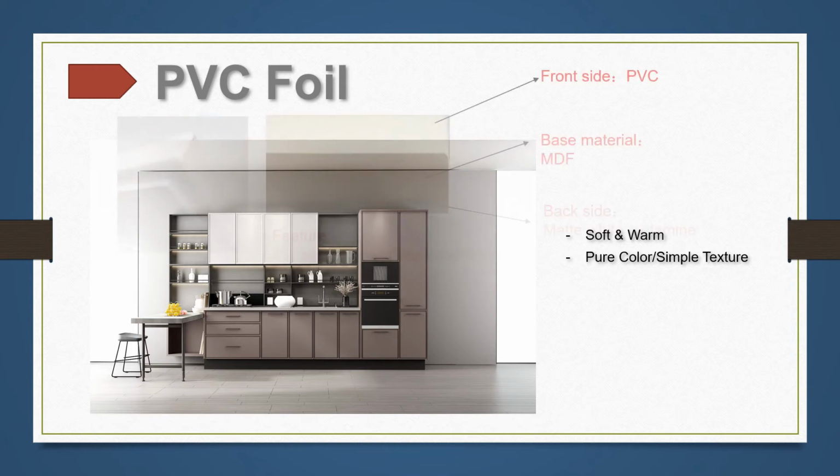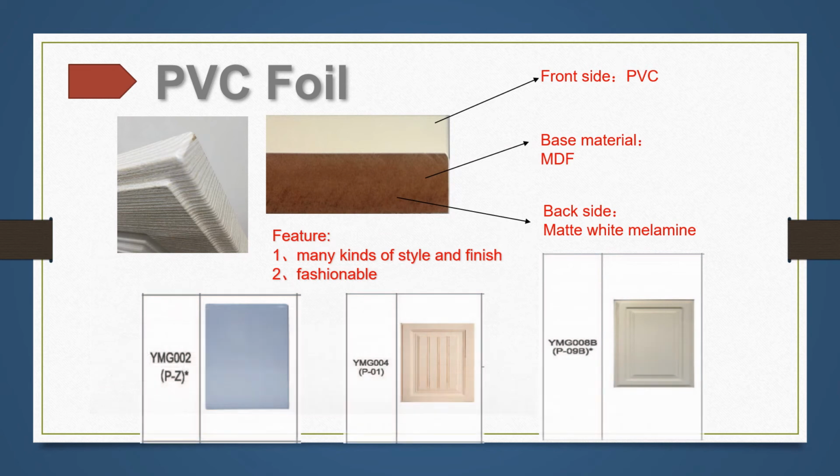Depending on the different types of ink we have, we get a variety of different melamine finishes. Some common types of finishes are pure color, wood grain, stone grain, fabric grain, and some other special grains. We can take a look at the sample here. The thickness of the melamine paper is around 0.1 mm, so it's nothing more than a paper. The base material is an 18 mm thick particle board, so the overall thickness of the melamine panels is still around 18 mm.